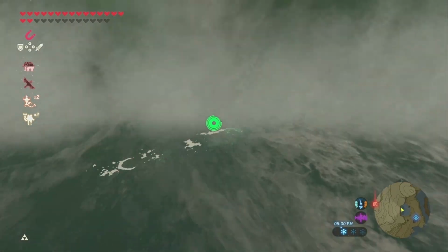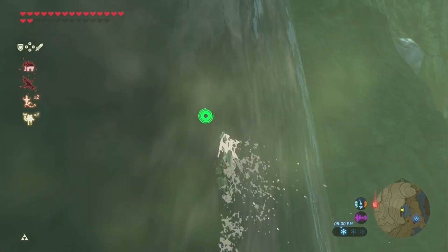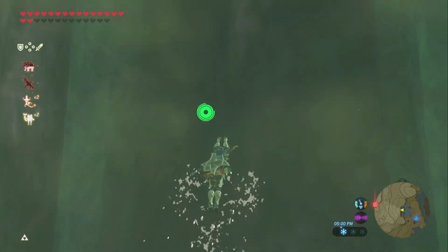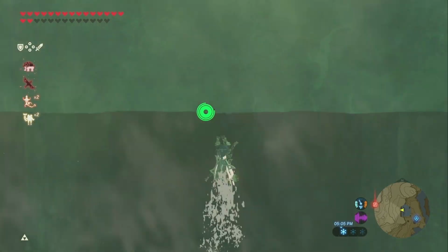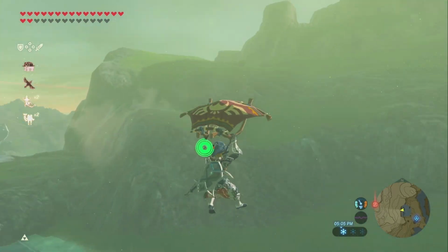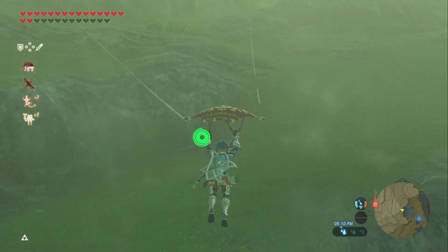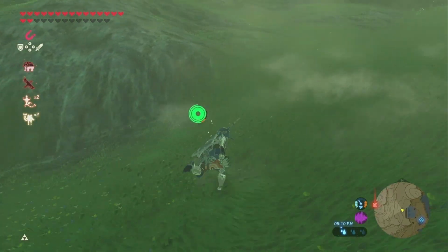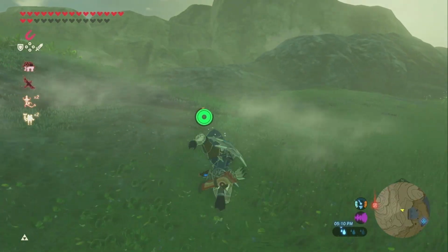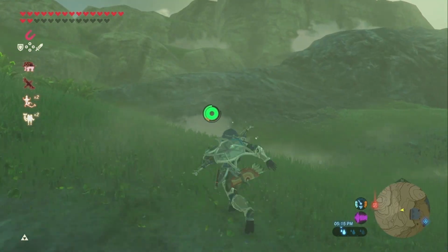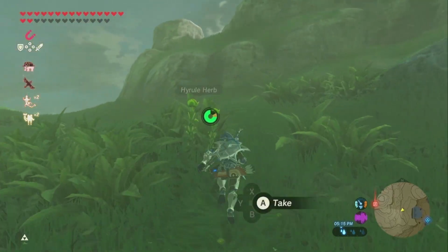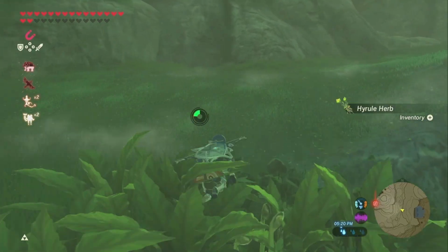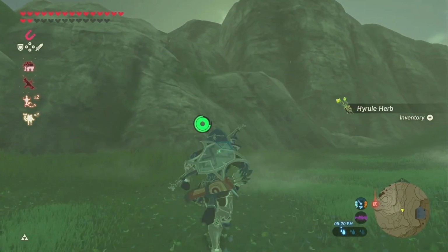Isolating and drain valves. Check for a cold water isolating valve and inspect for leakage. Check for a drain valve and inspect for leakage and or damage. Alright, no isolating valve. There should be an isolating valve on the cold water inlet in case the tank ruptures and floods.